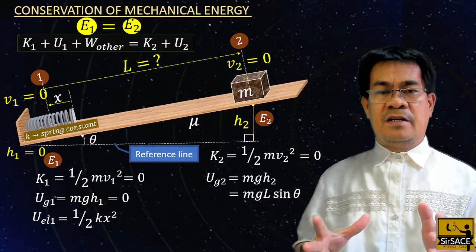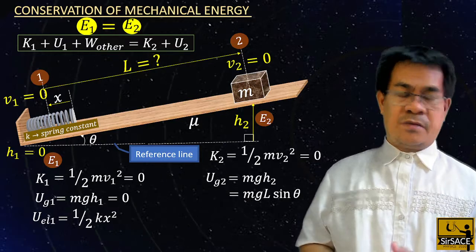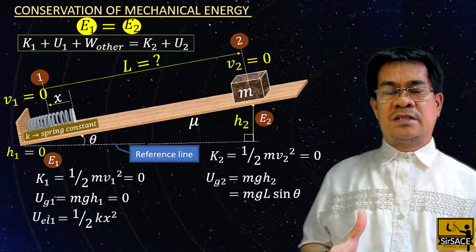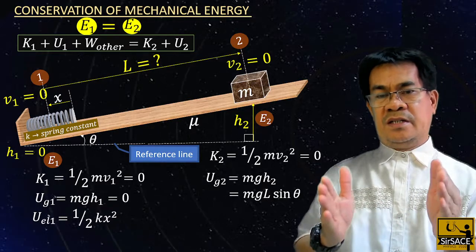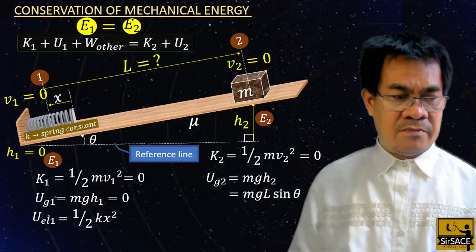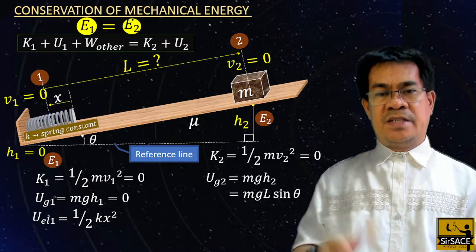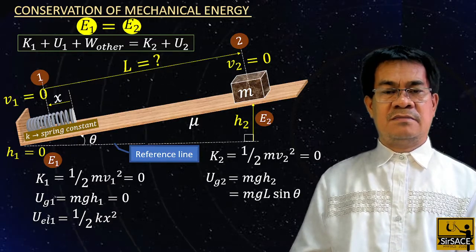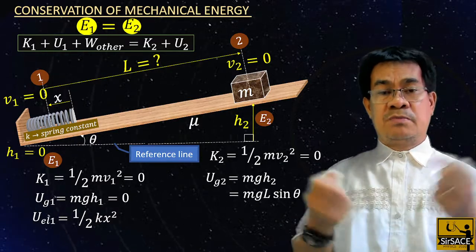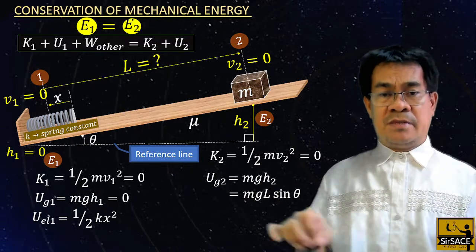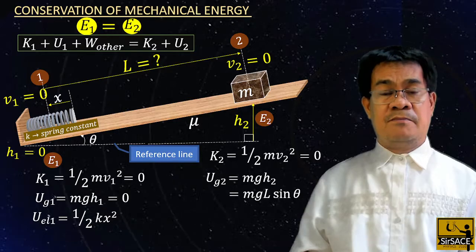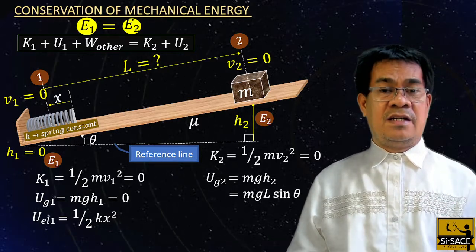So therefore, the requirement of using a spring is, in order to activate its elasticity, apply only a force within the prescribed force, and it depends upon the material. If you have a notebook spring and you apply too much force, then it will not return back because it is beyond the elasticity limits.